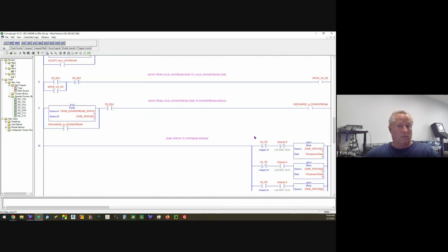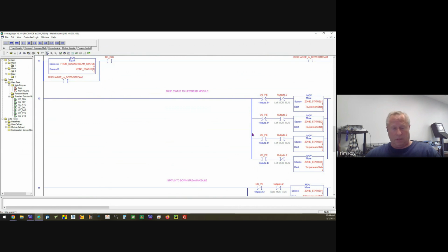And it does. I mean, you can write ladder programs and download it to the module, and the module will then work as a mini PLC. This is a way to maybe not have to buy an Allen Bradley PLC for thousands of dollars. You can put a couple of these programs in a couple of cards, and you're done. Depending on how you like to program, you can program in ladder logic, function block, and structured text.